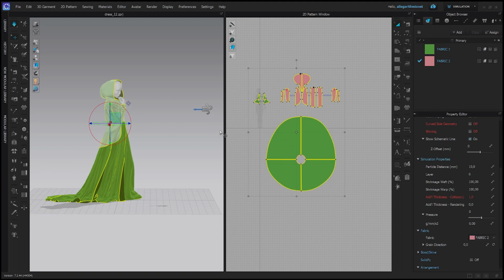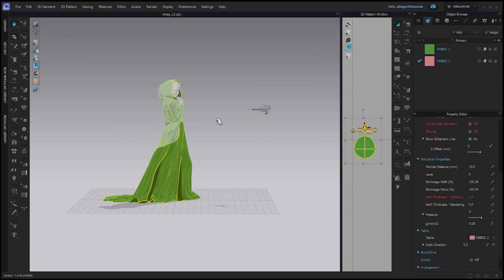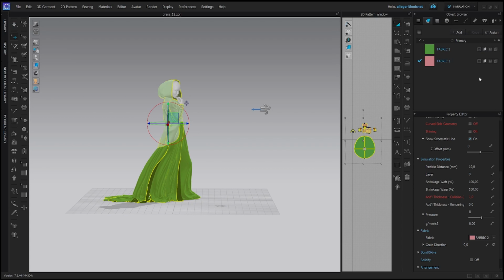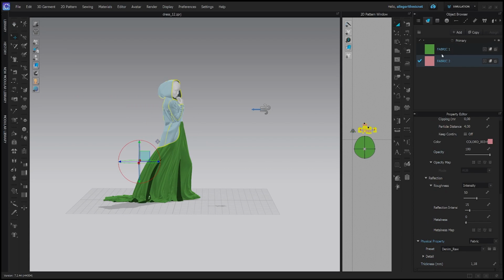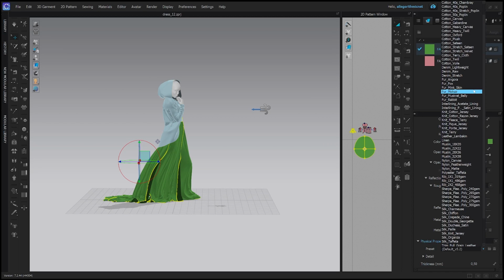Next, freeze all the parts you don't want to animate with the wind. In this case, I'm freezing the jacket and the upper part of the dress. You also want to make sure that you're freezing any garment that you want to apply displacement to in Unreal, as you can't apply displacement to animation caches. In my case, I'm freezing the jacket as it's supposed to be made from a rigid fabric, and I also plan to apply displacement to it.